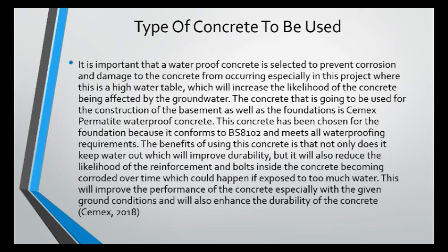Waterproof concrete will be used to prevent this. We have chosen Cemex Permatite waterproof concrete, as mentioned in the basement section also. This will allow our foundation to be more durable and prevent corrosion within the concrete and reinforcements.